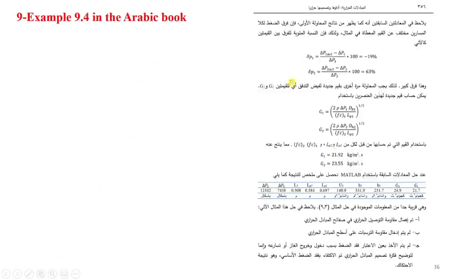We also compare the actual pressure drop with the allowable pressure drop for sides 1 and 2, and then proceed with another iteration for G1 and G2. So it is exactly the same but written in Arabic. And as we said before, we have some restrictions because we ignore the conduction in the plate, ignore the fouling, and consider pressure drop only due to friction.